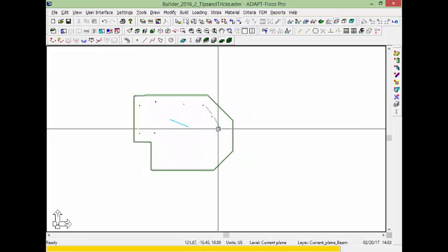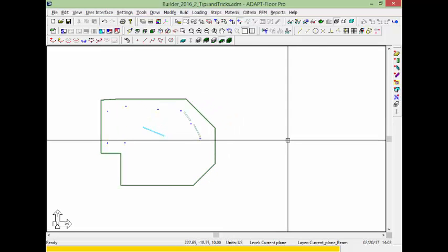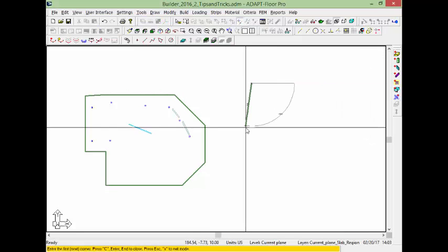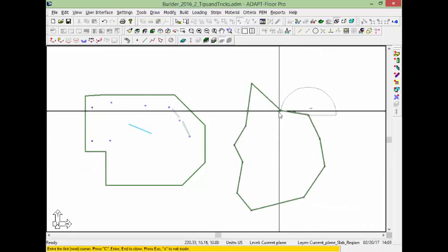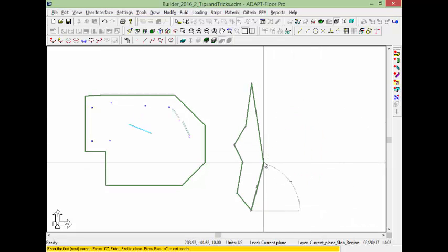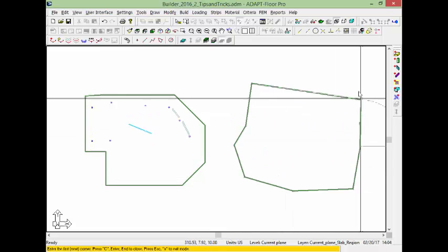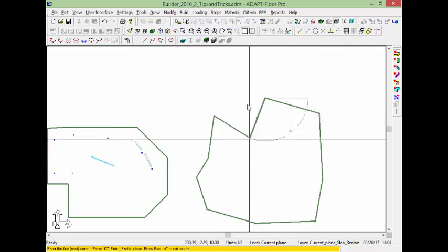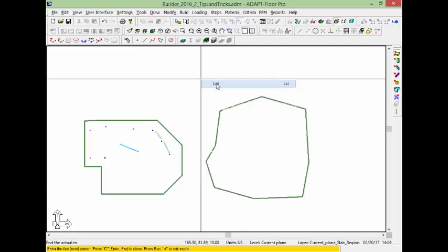I also have the ability to use the backspace tool when trying to correct a polygon that's been entered. So for example, if I go ahead and enter a slab, and let's say I click on the wrong point here several snaps back, I can select the backspace button to go back to that location and continue with my modeling. And this is useful for other components like area springs or area loads, for example.